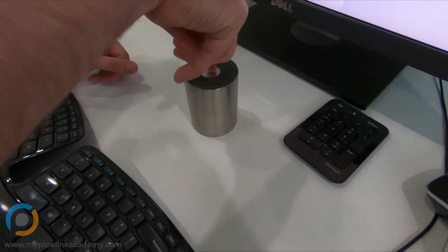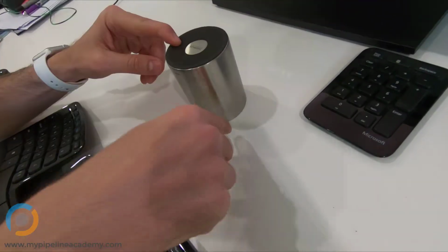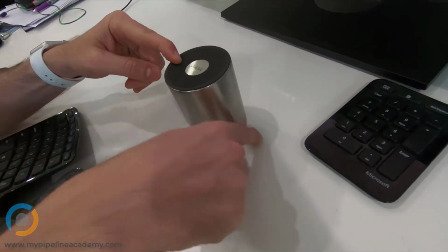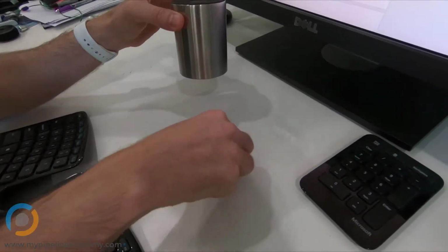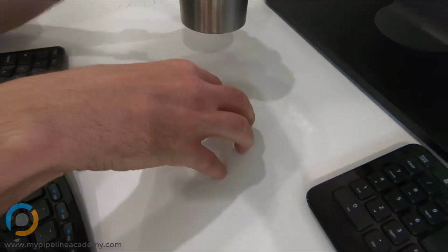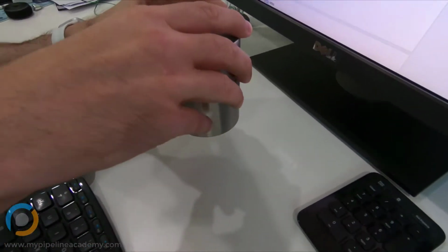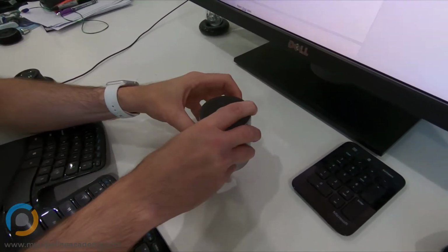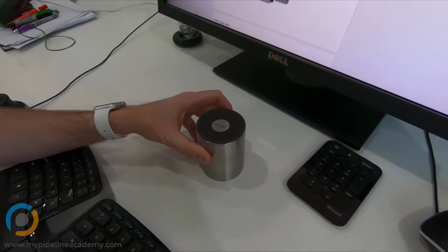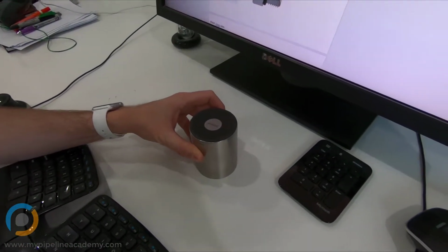So if I wanted to inject water in here and prevent that water from leaking out in the sides here, I would put, first of all, a little groove right here into the table, and then I'd put an O-ring in that groove, and then I would come down and place this cup on top. And that would be a face seal.